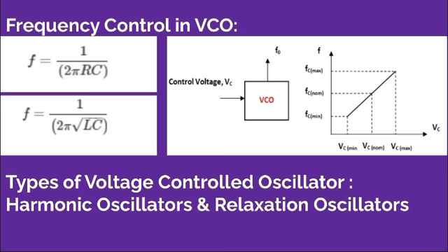The advantages are frequency stability with reference to power supply, noise and temperature, and accuracy in control of frequency. The main drawback is that this type of oscillator cannot be implemented effortlessly on monolithic ICs. Coming to the relaxation oscillators, the output waveform produced is a sawtooth. This type can give a large range of frequency using a reduced quantity of components, so it can mainly be used in monolithic ICs.